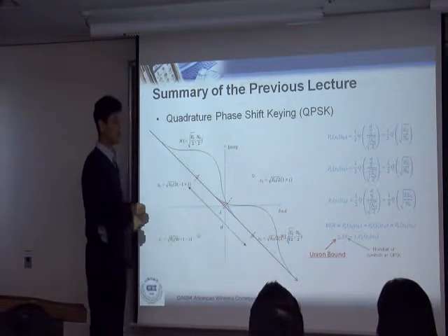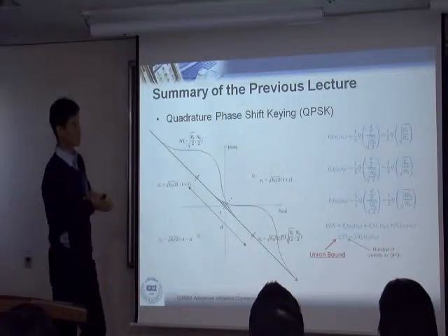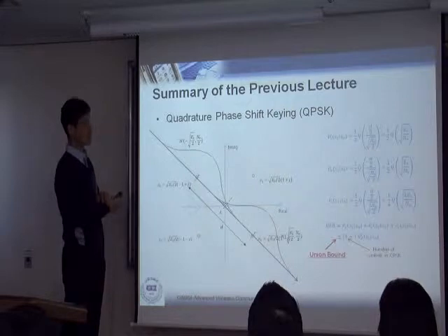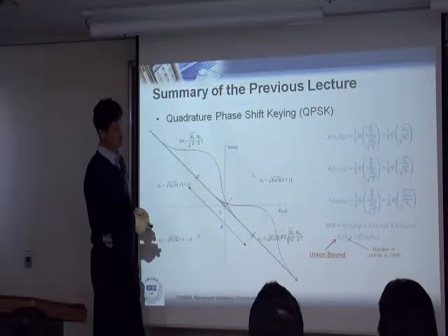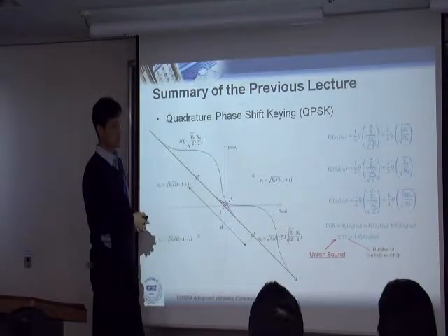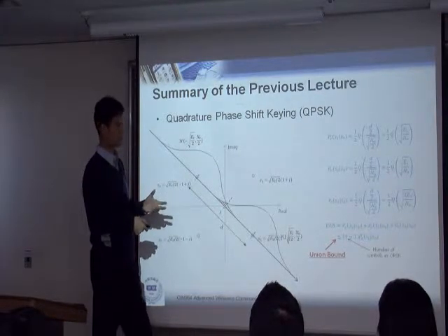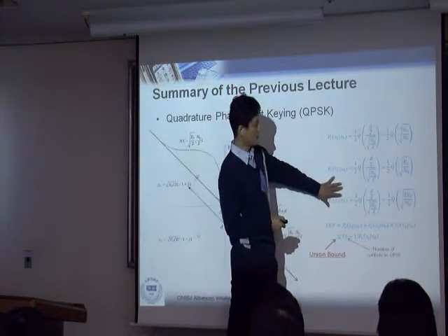You don't want to calculate the exact one. Sometimes it is not possible. Therefore, pretty much no one tries to find the exact BER, which may not be possible. What people do is use a bound. Among those many bounds, people use the union bound. The union bound is like overestimating your BER. So in this case, we have 3 different things.